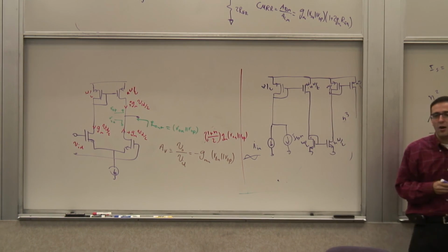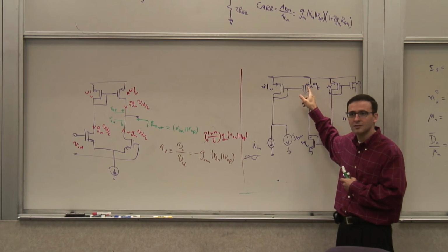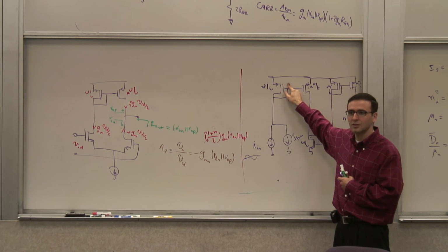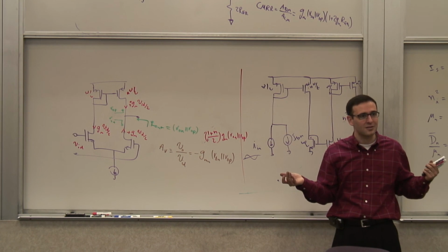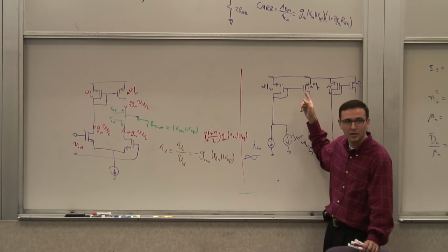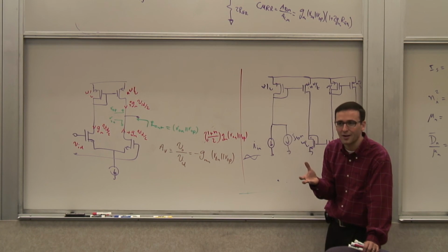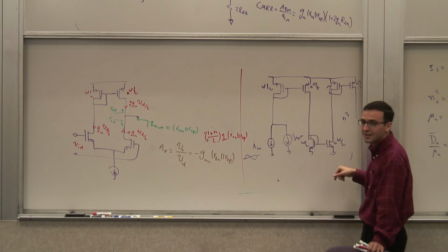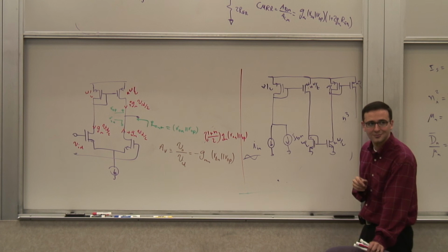Right? So now, I can make each one of them the cubic root of what I needed before, and therefore these are not huge ratios, so the capacitances don't become incredibly large. So let's say I'm trying to get an amplification ratio of 1,000. I could get it out of 1 to 1,000, and the capacitance would be 1,001 times that CGS. So let's say 1,000 times the capacitance. But now, if I make it out of three tens, it's 10, 10, 10, this is 11 CGS, this is 11 CGS, this is 11 CGS. Then you have 1,000 times DC current also. Right, yes. Yes, correct.